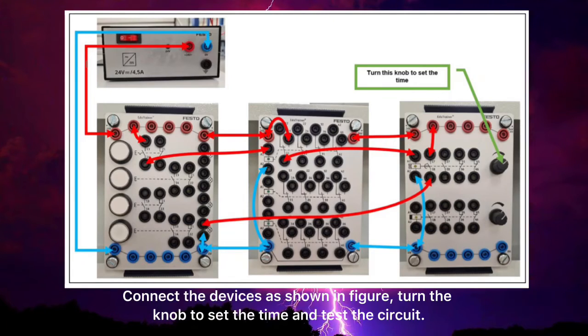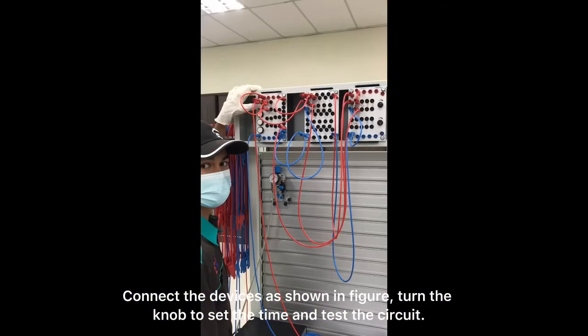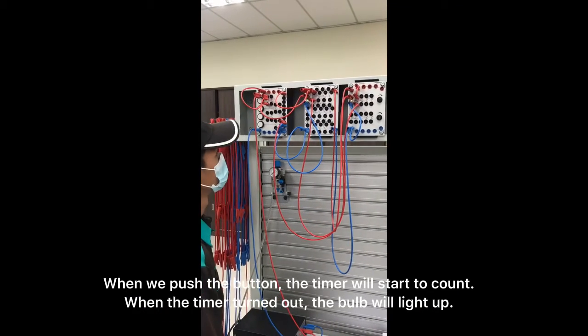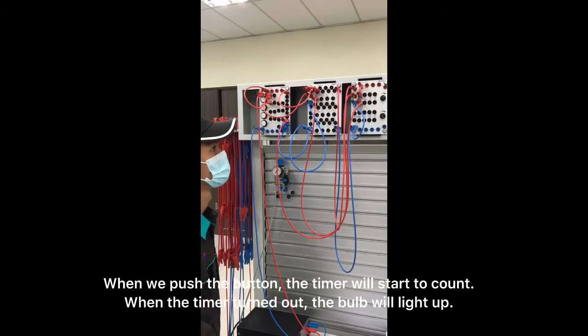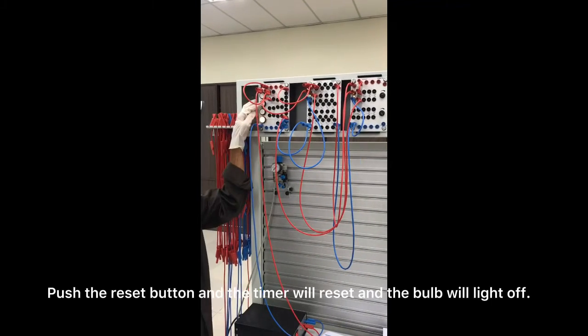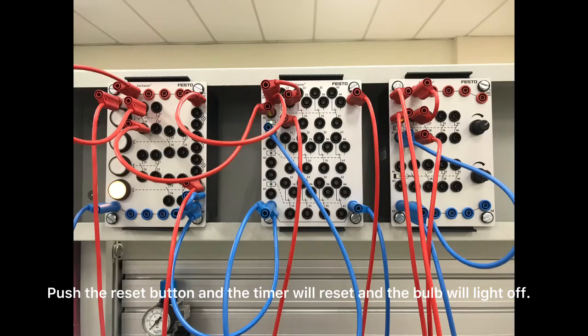Lab Activity 2, Basic Timer Circuit, Task 2A. Connect the device as shown in the figure. Turn the knob to set the time and test the circuit. When we push the button, the timer will start to count. When the timer times out, the bulb will light up. Push the reset button and the timer will reset and the bulb will turn off.